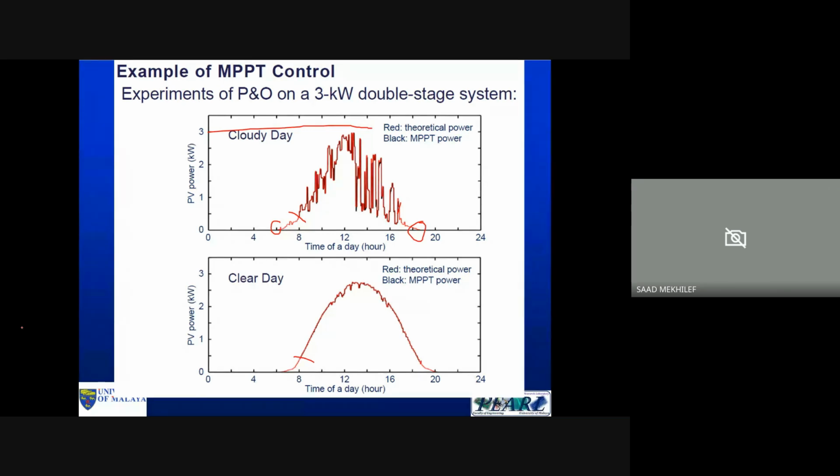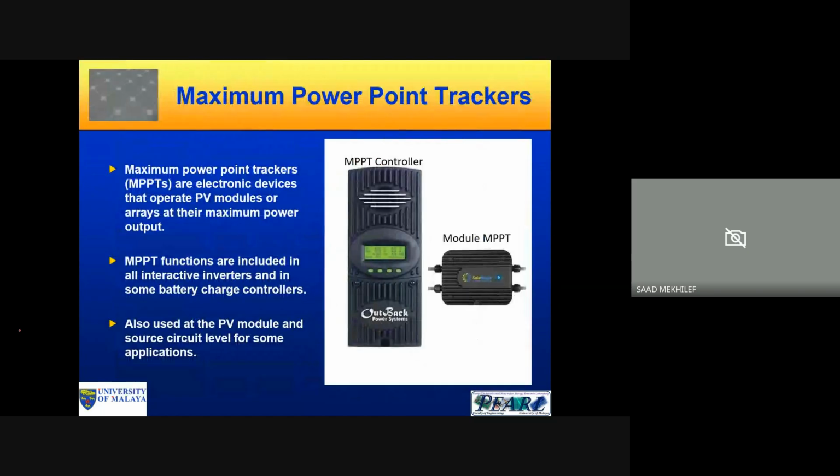So instead of disconnecting, we can send control signals to all these MPPTs to operate at 50% of their power. So they block the amount of power, and only 50% goes through. That's actually the importance of having the FPPT now, because MPPT is still in use, okay? And these are some examples of hardware.